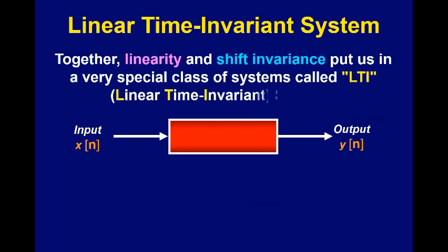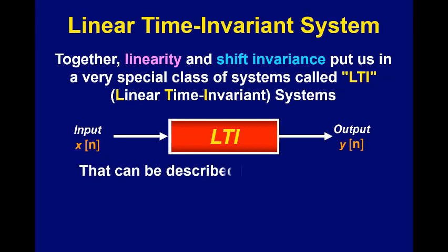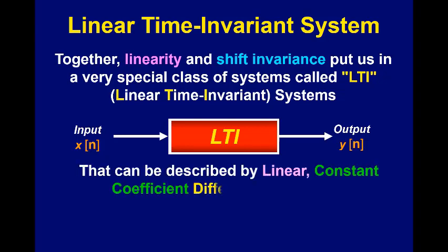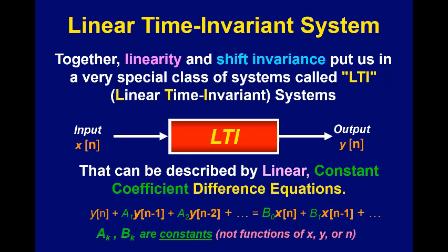That gives us a linear shift invariant system, or linear time invariant. We're going to call these LTI systems, just like we did in 228. Those are the kind where all of our good things work: convolution and transforms all rely on having a linear shift invariant system. If they are both, then I have just y terms and x terms, and all the numbers that go with them are numeric constants. So we have a linear constant coefficient difference equation.